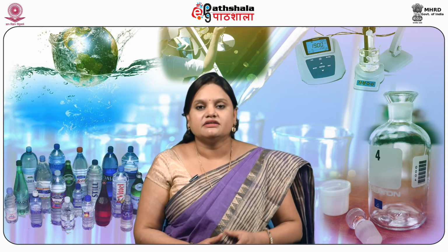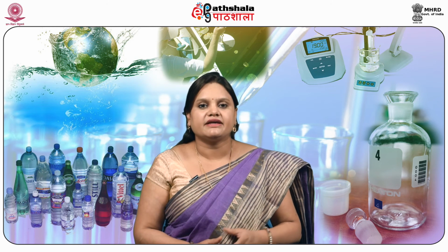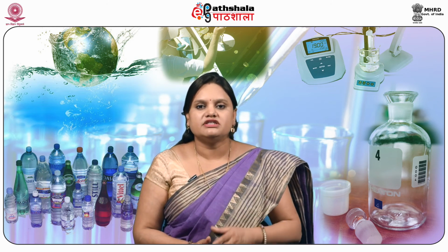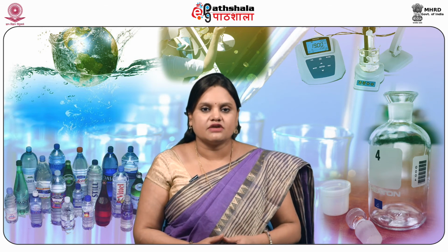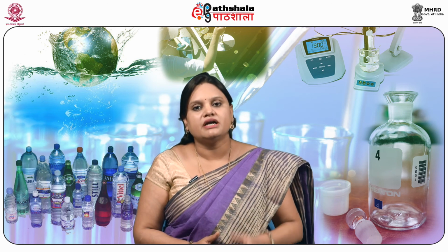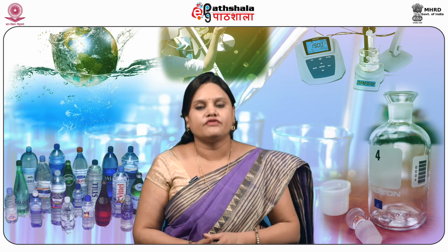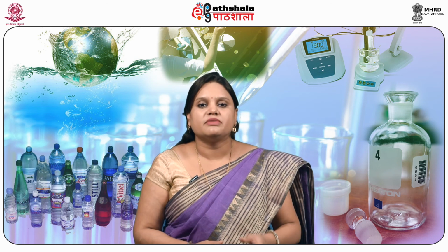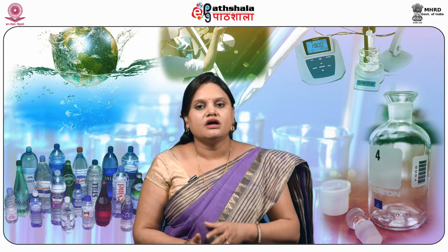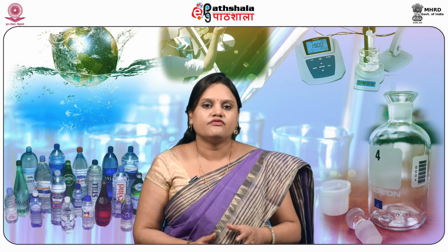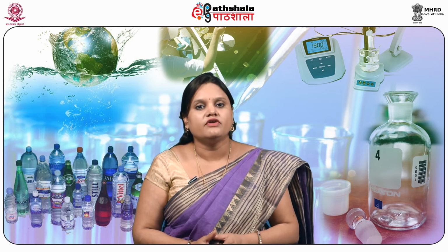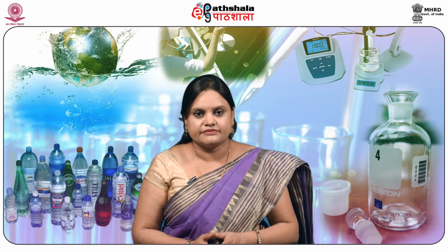In this method, multiple burner equipment can have part of an array of the burners with some burners out of service, not feeding fuel but supplying air or flue gas. This allows the burners around them to supply fuel and air to the air or flue gas flowing from the burners out of service. BOOS is the short form of the burner out of service method.